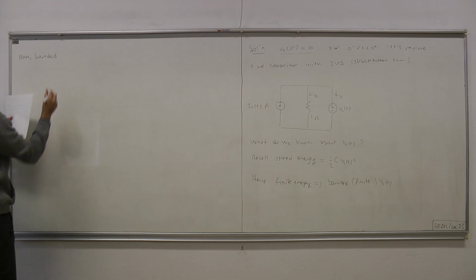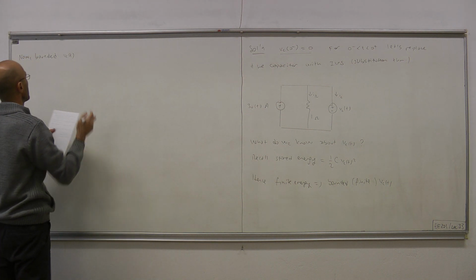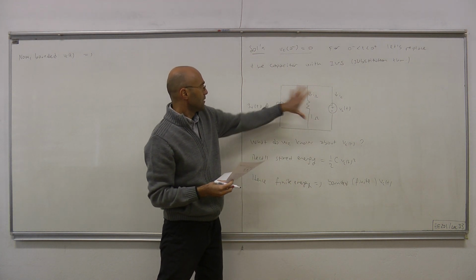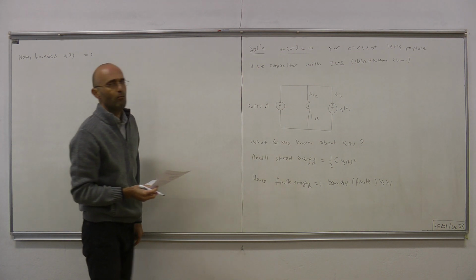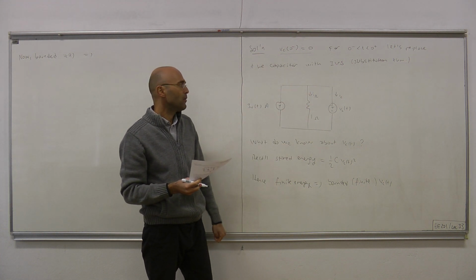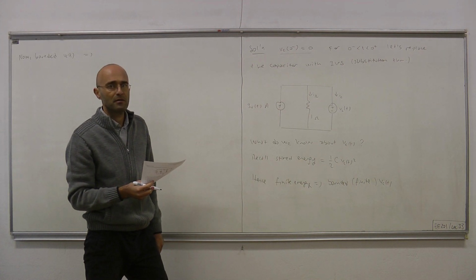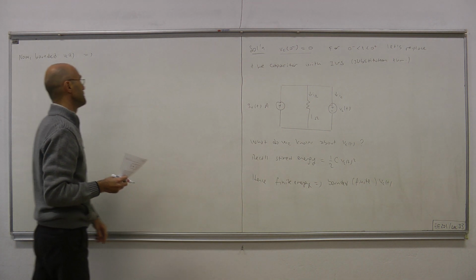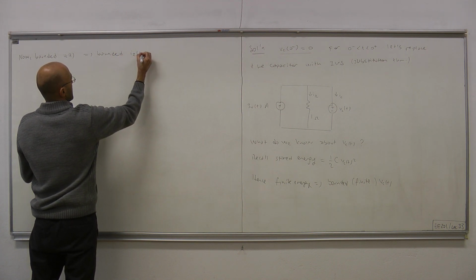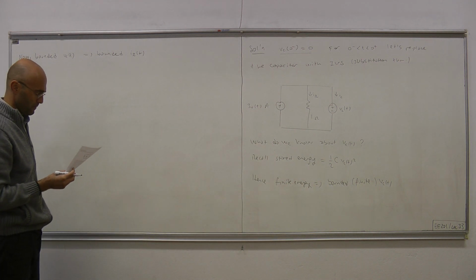Our starting point is that VC(t) is bounded. So that implies, because everything is parallel in this circuit, the voltages of all the components are bounded. Especially the voltage of this resistor is bounded, and therefore, by the terminal equation, its current must also be bounded, because current is the voltage divided by the resistance. So bounded capacitor voltage implies bounded resistor current.